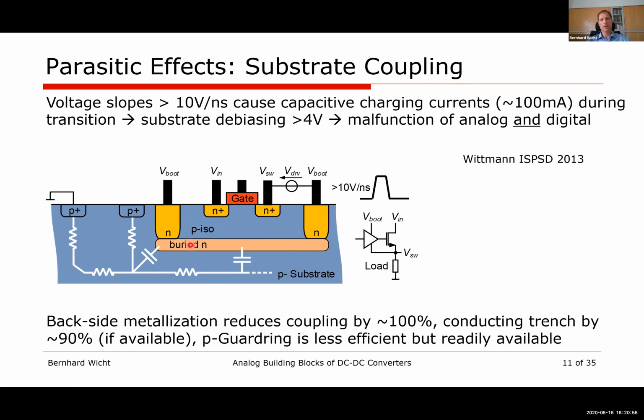So this looks similar to what we have seen, but this is now a power stage, which shows exactly the switching waveform. In the end, that's already linking to what we will talk about in a few minutes, but it's probably quite straightforward to see that there is a switching node activity. And with that, we have this whole isolation well, which is required to move up and down at very steep slopes. And this reverse biased junction here is also representing a relatively large capacitance.